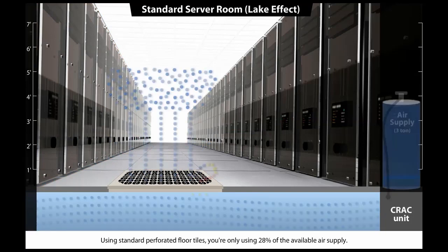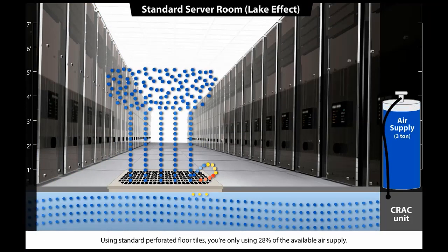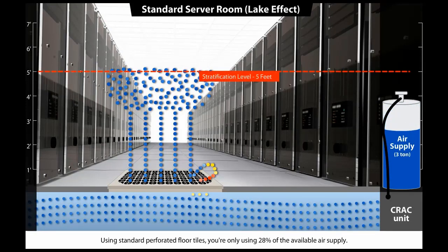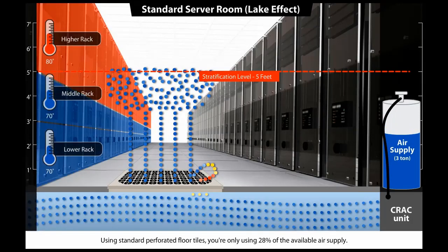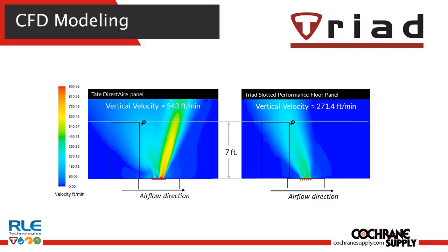As rack inlet temperatures continue to rise near the bottom of the rack, the server fans begin to ramp up, increasing overall energy consumption. Alternatives such as increasing plenum supply pressure also drive up overall cost of energy to operate the data center by driving the existing fans harder or adding additional CRAC capacity.